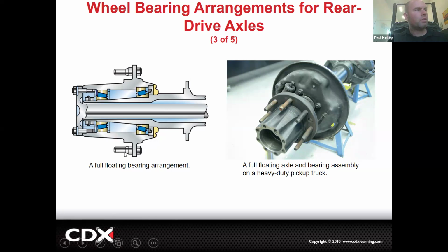See, these are the wheel studs. So if the wheel studs are here, the wheel is basically sitting on this whole hub right here, which is this, by the way. Cool, that's what that is. And then do you want all that stress on this axle shaft that goes into the differential? Your answer would be no, not unless you want to bust that off. A non-floating axle will literally just have a flange attached to the axle and all the weight's on that flange. If you put so much weight on that, you could shear it off or bend it. The non-floating would be fine for the 1500 or maybe even a little smaller.